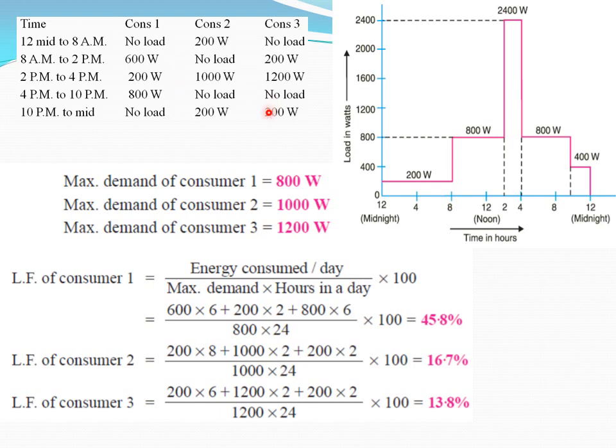In this example, we are going to find the demand factor and the load factor given the amount of connected load and maximum demand and the units generated per annum, that means in a year, they have given you. So these are the given details. If you know the formula, you can directly apply. The demand factor formula will be the maximum demand to the connected load. So maximum demand is 20 megawatt and the connected load is 43 megawatt. So you will be able to get the answer.